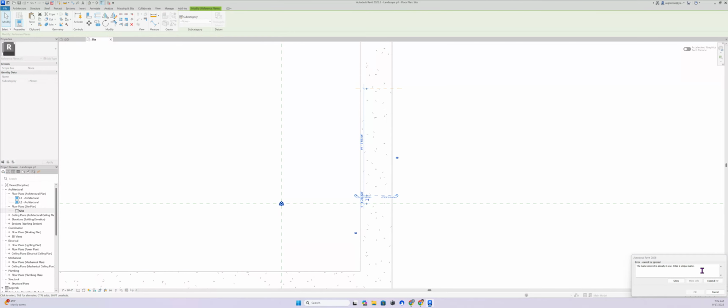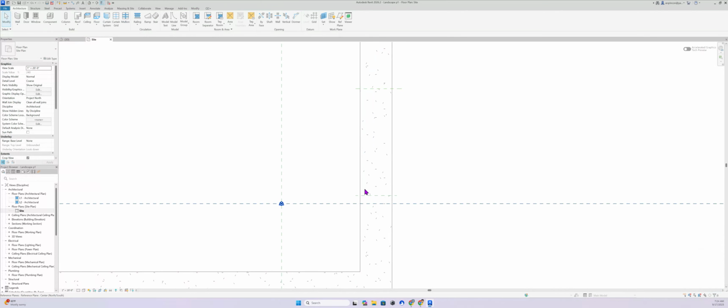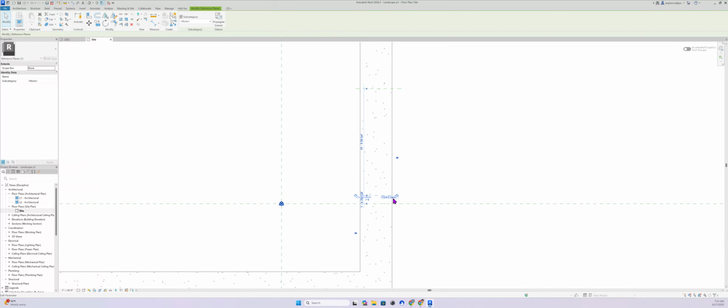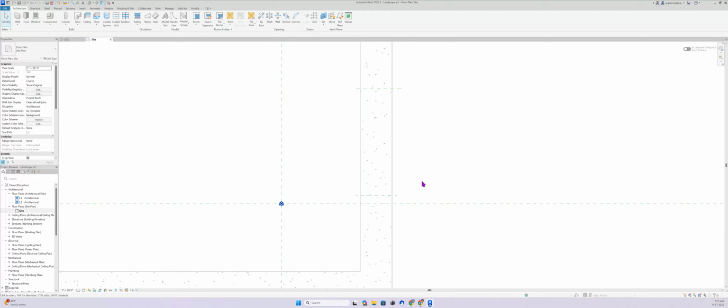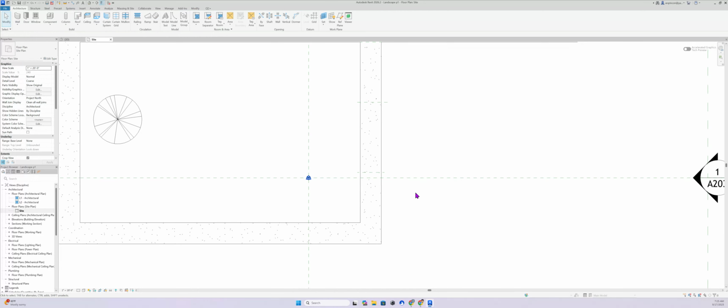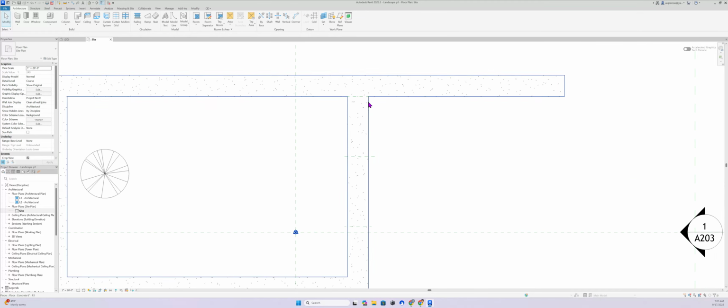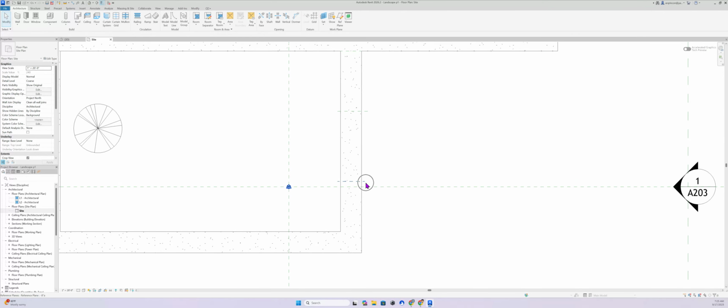And then it's gonna tell you that this name already exists. Okay, great. So let's cancel this. Let's get this one, right? And put here, again, minus 8 inches and then a letter A. Got it? Okay, so it's the subsequent. There we go. So we're gonna go and slope down minus 8 inches here, minus 8 inches here as well. And then here, I'm gonna draw another reference plane to finalize this.